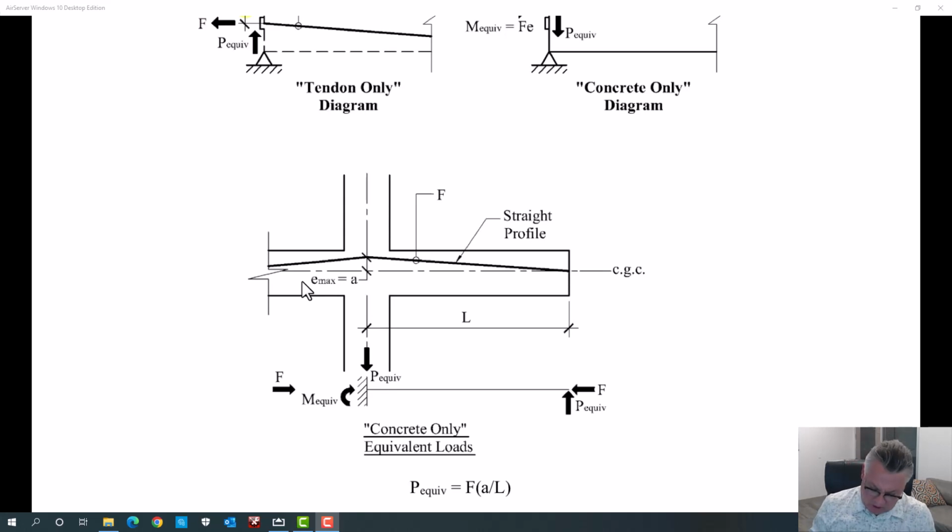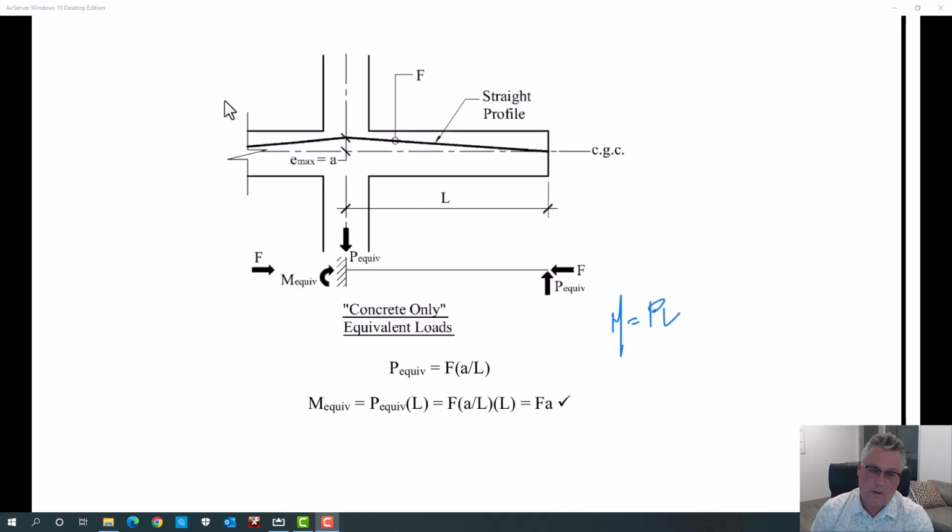In cast-in-place concrete, you can certainly do this, but this will start to sag over time, a lot of times. And in pre-stressed concrete, we can actually balance that cantilever load. So we can make that straight and flat, or as straight and flat as we feel like it. So we love cantilevers in pre-stressed concrete. It gives owners and architects all kinds of freedom to do fun things and get the columns away from the edge of the building and cantilever distances out, and a lot of people like that. So let's look at the cantilever.